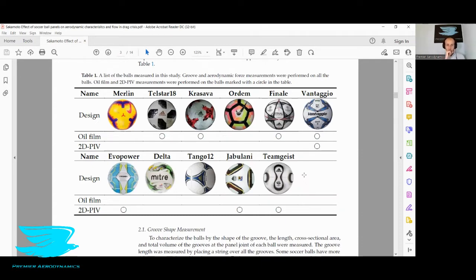So the drag crisis that occurs for soccer balls, that's mainly due to a massive change in pressure drag. And that occurs because the flow stays attached longer, which means that there's a smaller wake. There's a higher pressure on the back surface for a lot of it. So that equalizes the high pressure on the front surface. And that's why you get a drop in drag. There's not such a big drag difference.